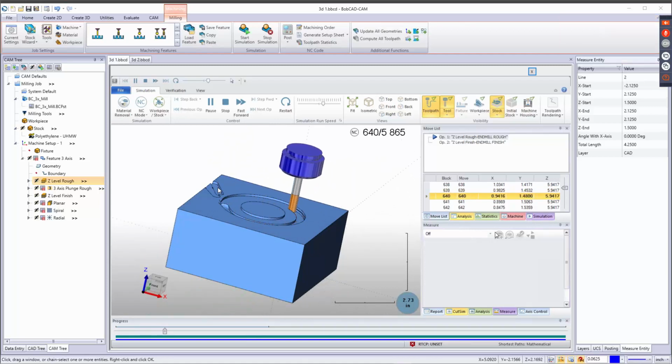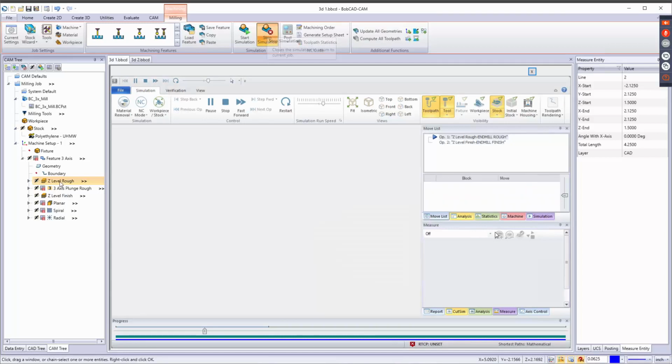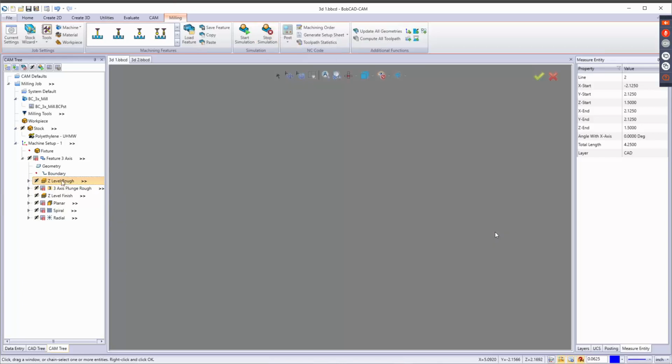If we used a plunge, I would have had a different view in there. Yeah, it's ramping. You know what? I'm not liking that. And I didn't set anything up in the ramp anyways. So I'm just going to change that back to plunge and recompute it.